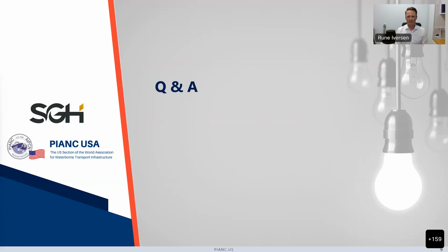Our next question is, in regards to hull pressures, are there also guidelines relating to ship's hull form, like belting, included or updated? Yes, there will be. There will be guidelines on how to deal with belting, and it really changes the load on the fender panel. Instead of getting a surface load, you might get a line load on the panel and really develop high moments in the panels, but there are guidelines for how to deal with that. Okay.